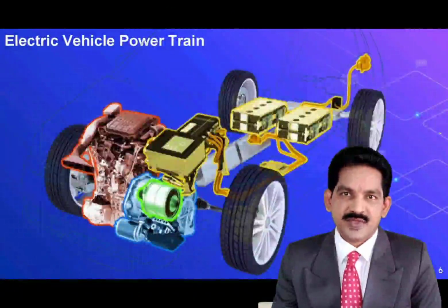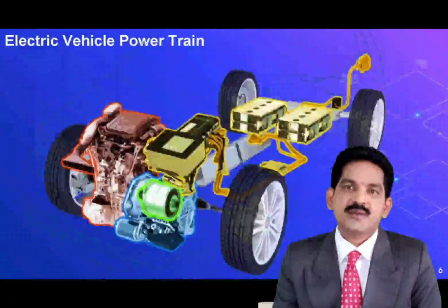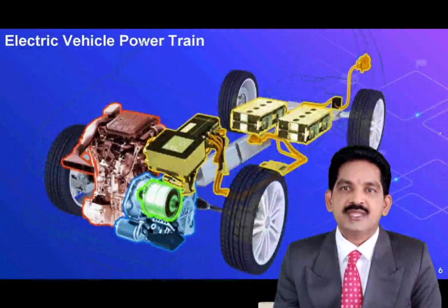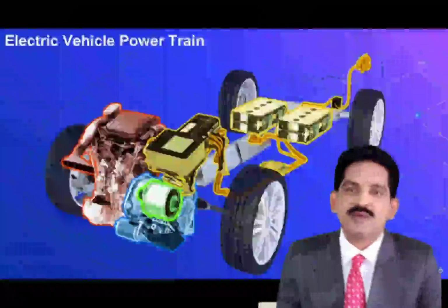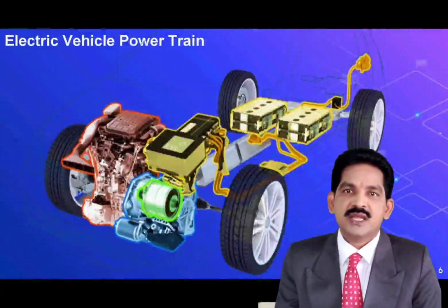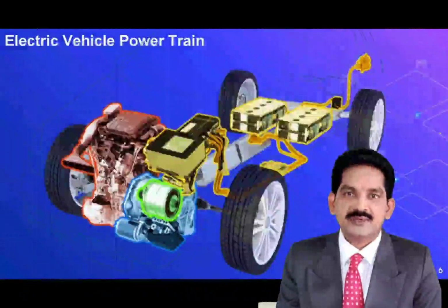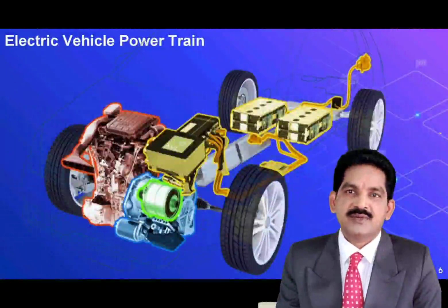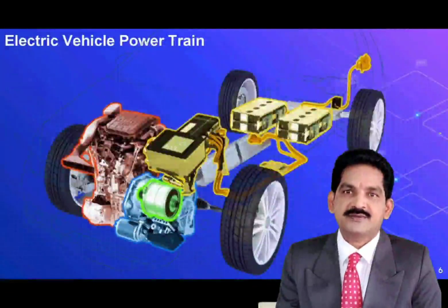In this figure, a single EM configuration with a gearbox and clutch is shown. It consists of an EM, a clutch, gearbox, and the differential. The clutch enables the connection or disconnection of the power flow from the electrical machine to the wheels. The gearbox consists of a set of gears with different gear ratios. The advantage of this configuration is that the weight of the transmission is reduced.